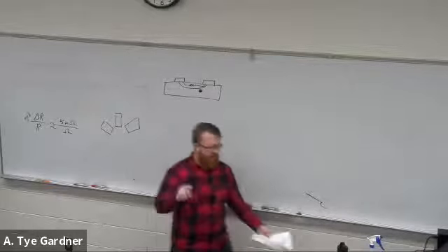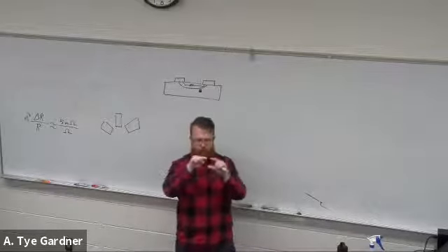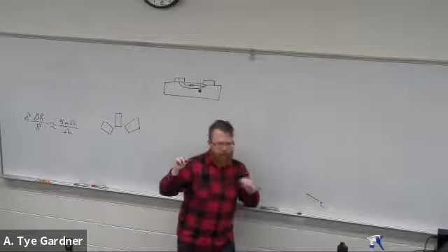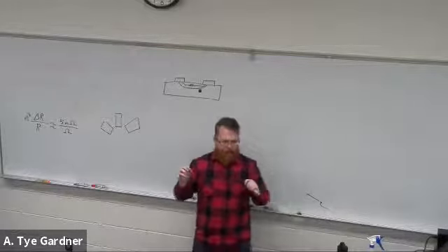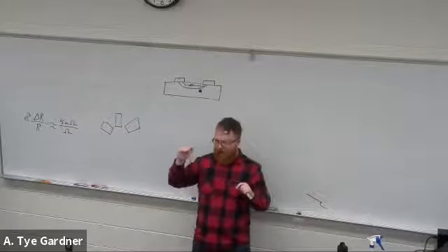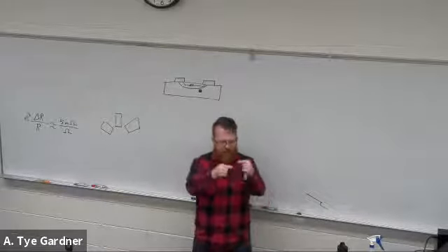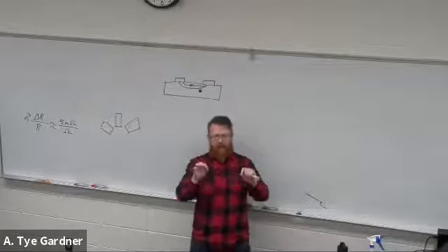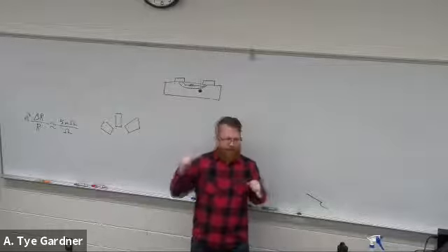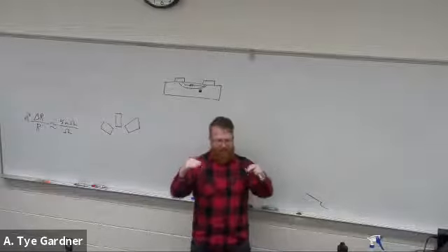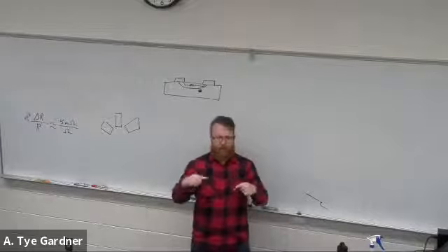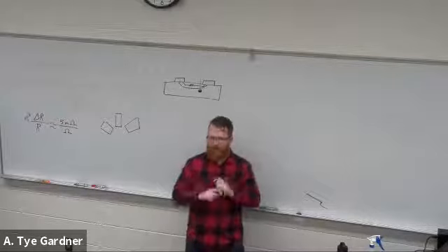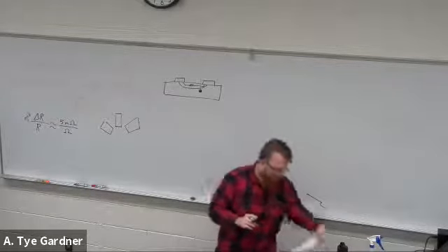And then I'm going to have you guys actually do some measurements where you're going to start by measuring just known weights. And we're actually not going to use a strain gauge. We're going to use a force gauge, which I'll talk about in a little bit, because they're a little bit easier to work with. And you guys will measure that change in resistance. You'll calibrate it with little calibration weights so that you can know what it is. Measure some, then use it to measure some unknown weights. And then we'll start playing with the temperature. I bought little heating pads that we'll set underneath, and we'll use the bridge to compensate for the change in temperature, right? So we'll get some hands-on measurement for this type of bridge circuit.